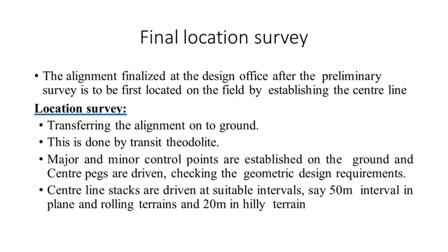The final location survey, त्याचा purpose काय आहे? What is the purpose? The final location survey is to lay out a final center line of the road. Actual field वर आपल्याला final center line जी आहे रोडची ते आपल्याला layout करायची आहे. Okay, so what is the basic purpose? To lay out the final center line of the road in the field based on the alignment selected in the design office. Okay, next, the two operations involved in this survey: the first one is theodolite survey and the next one is detail leveling.